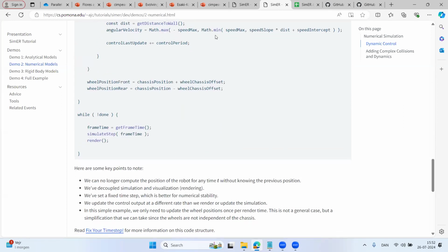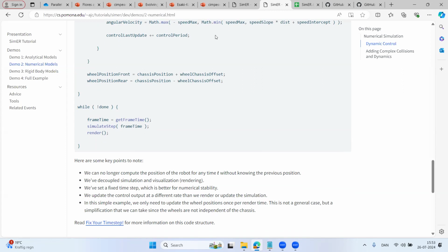I just threw some terminology out there. By stable, I mean numerically stable: it's not going to end up with this thing flying off into space. How many of you have done some sort of evolutionary robotics experiment before with rigid body dynamics, for example? Okay, keep your hands up if you never had the simulation explode. Okay, no hands are up anymore. So that's a pretty common thing to have happen. You get some weird numerical instability. RK4 is pretty good at not having numerical instability. Just more computational workload though.